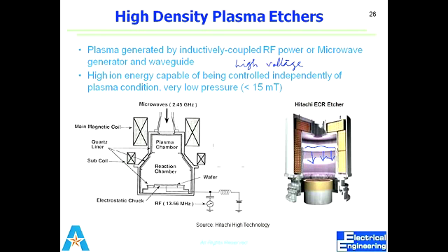Similarly, if you know the etch rate, you should decide what the passivation layer thickness should be. For that much time, you put the passivation layer on, because the deeper the thickness, the longer is the etching cycle, so the longer should be the cycle for the deposition.